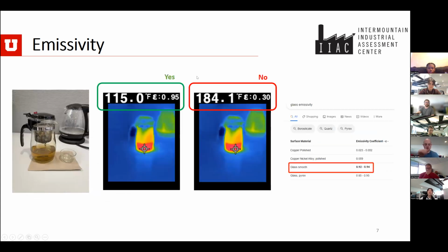So here I just want to emphasize why the emissivity is very important, because yesterday I checked the historic thermal camera pictures from the SD card. I can see most of us didn't set up the emissivity correctly. So we can see the epsilon here. Here is the emissivity. So after you take a picture, you can see the emissivity here. So here is my teapot. I just did a very little experiment today.